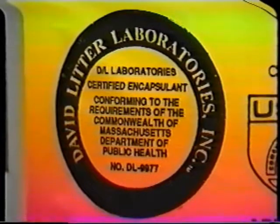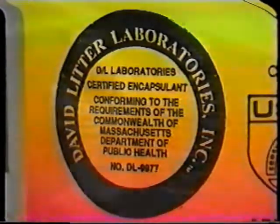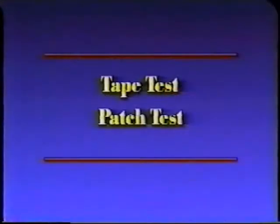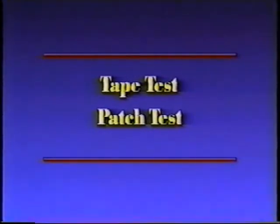Massachusetts was one of the first states to develop regulations that outline the steps to take to determine the suitability of applying a particular encapsulant as a lead hazard control treatment. The following guidance summarizes the suitability tests required in Massachusetts. Two simple tests determine whether the use of an encapsulant is appropriate. These tests are the tape test and the patch test.